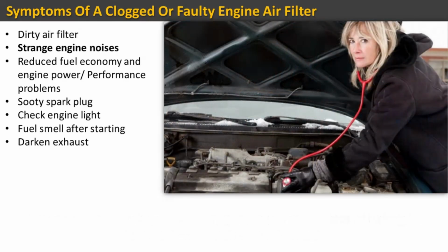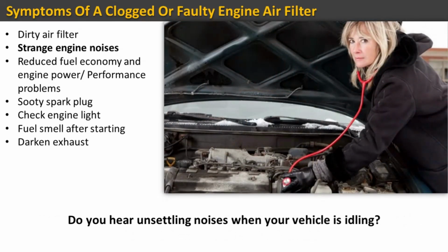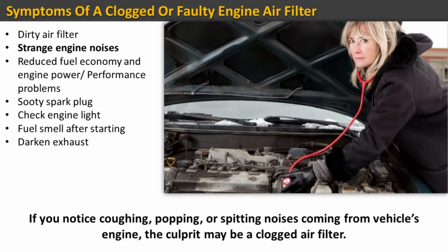Strange engine noises. Do you hear unsettling noises when your vehicle is idling? If you notice coughing, popping, or spitting noises coming from your vehicle's engine, the culprit may be a clogged air filter.